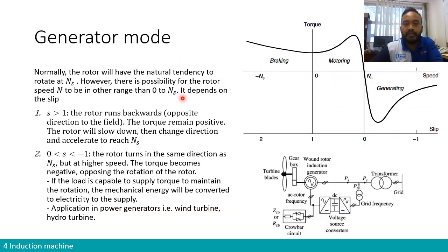Okay, so now we have seen most of the generalities of the operating principle of the machine in normal mode, what we call motoring mode. If you look at this graph over here, torque versus speed, at the bottom we have, as usual, the axis for the slip. The curve that we have discussed just now is basically this part of the curve over here. It is the curve when the motor is functioning in motoring mode, when you have your slip, positive slip, from 1 to 0.